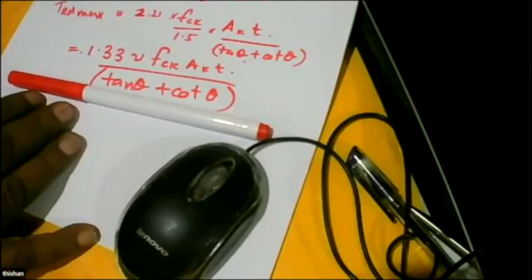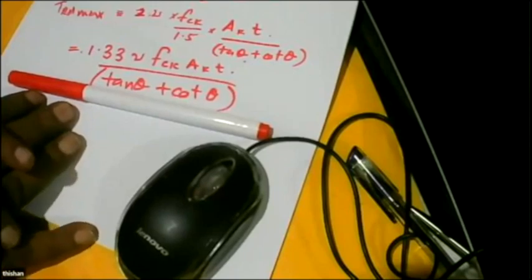Is that clear, Mandugopi? Because if it is a cantilever and the eccentric load is applied, it is a statically determinate system. Then you know the torsional moment at the place where the cantilever starts. What do you have to do? Just design for that torsional moment.